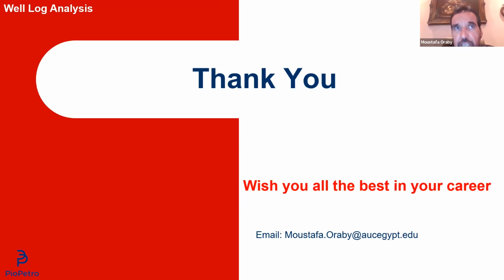It's very complicated, as it is in neutrons, very complicated as it is even in the gamma ray corrections. So having a density measurement that has very, very high sensitivity to any type of variation in the wellbore. If you put the casing and you put the cement, it will add much more difficulty for the density. Up to my knowledge, there is no density through casing anyway.